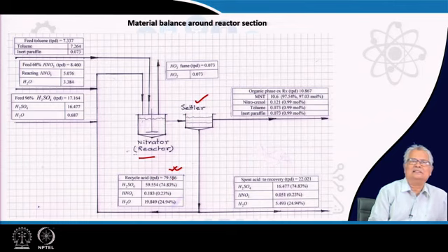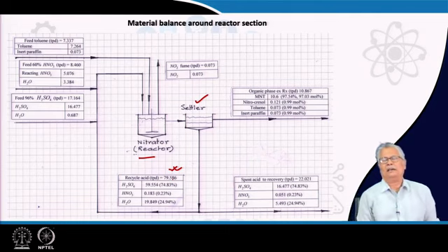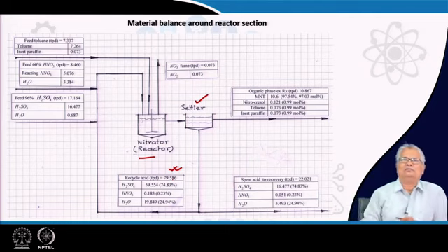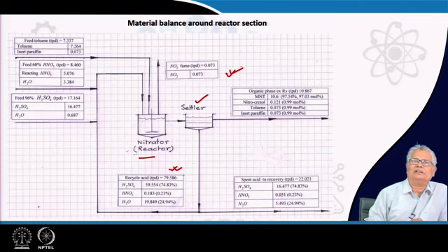The reason is that the ratio of the acid to your toluene has to be high, and it has to be maintained at a specific rate which is arrived at through a set of calculations. You will also note that a good amount of fume has to be disposed of every day. It amounts to about 73 kgs a day.